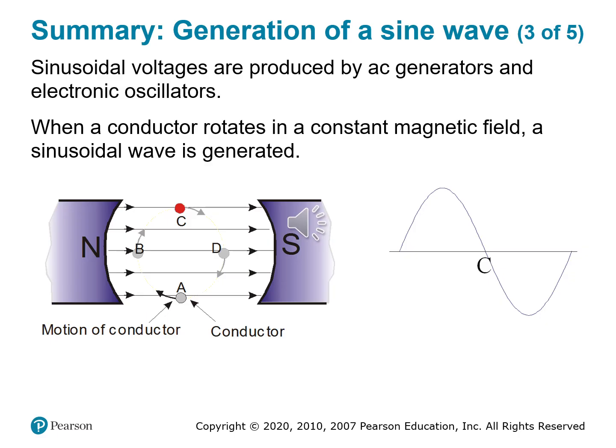And you're saying, why? Because from here on, the conductor begins moving back down, changing the direction in which it cuts through the magnetic field. That's what makes AC truly alternating. Both the magnitude and direction of the voltage change in a smooth, predictable rhythm. What you're witnessing is the symmetry of the sine wave in motion. Each quarter turn marks a key change in the waveform's direction and strength.